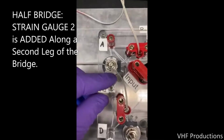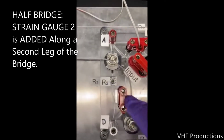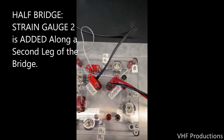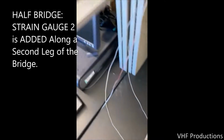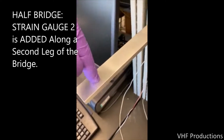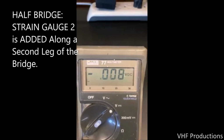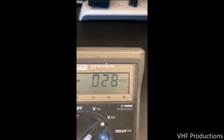As this strain gauge will go into compression equal to the tension on the top side, it effectively works as an amplifier. It increases the resistance change in the circuit, and therefore when we try to deflect the beam again and look at the output of the circuit across pins B and D, the output will be amplified by adding that second strain gauge. We get a much larger output voltage for the same general deflection.